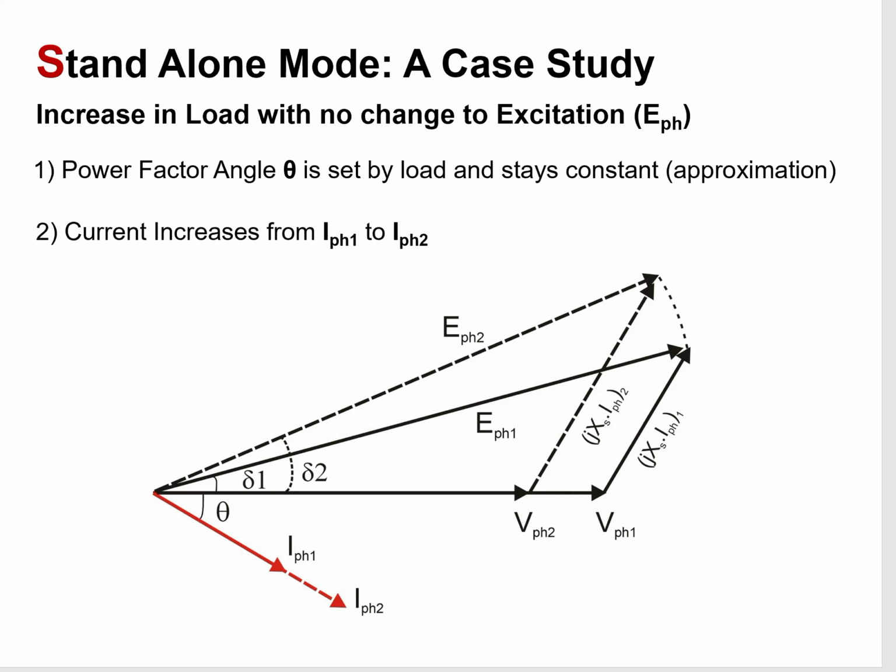Generally, when a load on a synchronous generator is added, the following changes can be observed. First, for lagging loads, the phase voltage decreases significantly. Second, for unity power factor, this means that we have a purely resistive load, the phase voltage decreases slightly. And the last case, for leading or capacitive load, the phase voltage rises. In all cases, this will cause a change in the load angle as observed over here.